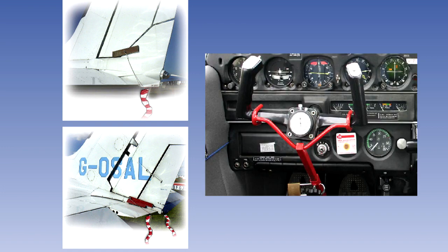When an aircraft is parked in the open, strong or gusty winds could blow the controls against their stops with sufficient force to cause mechanical damage. To prevent this occurring, control locks are fitted. These may be external or internal, and may be fitted to the control surface or to the cockpit control. If they are fitted to the cockpit control, they may be arranged so that it is impossible to open the throttle until the control locks are removed. External locks have high visibility flags fitted. Obviously, all locks must be removed before flight.